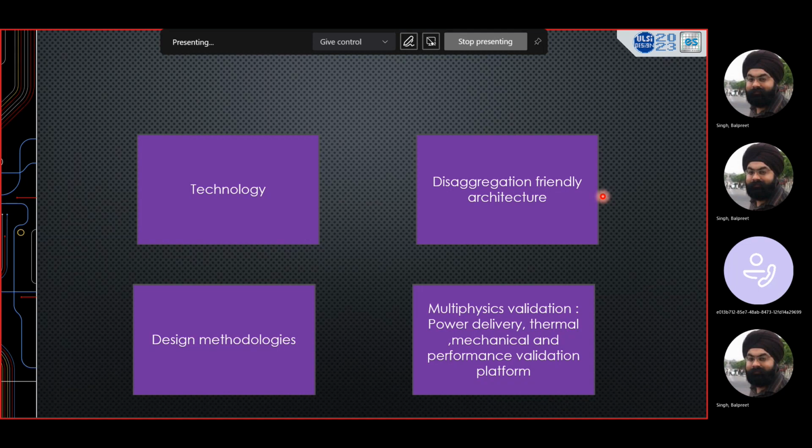So that's the technology innovation needed, and every company is spending time and energy to make it predictable. The TSV technology, how do you make it? And the best microbump technology is what? There is no microbump. That basically means you make the two dies, put them on top of each other, and they get connected, maybe keeping a marker, a couple of 2-micron markers.